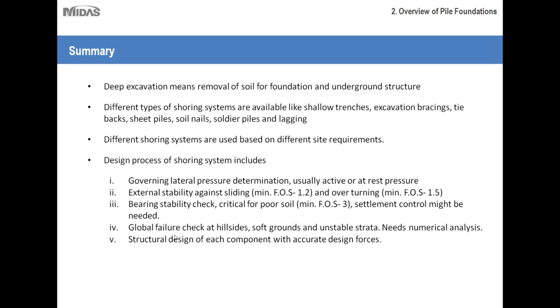And then the structural design of each component with accurate design forces. Your final step, after you've determined your minimum factors of safety as well as your earth pressure and your earth conditions, is to design the structure itself. What you need to do is check the forces acting within your support systems, just to make sure that they're safe, that they meet those minimum factors, or that they don't go past a certain critical state.